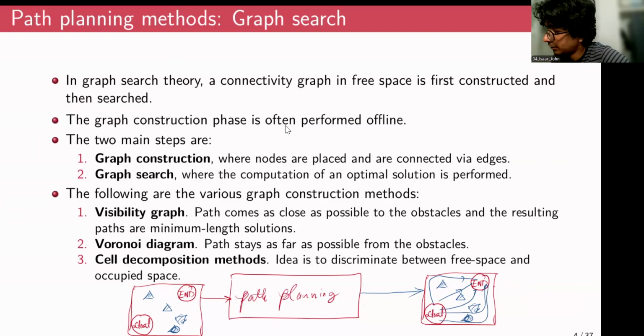This is what we expect from the path planning algorithm, right? Multiple paths. And you may call these road maps, a network of multiple trajectories within that map. And while it has to create this sort of roadmaps, all possible roadmaps, it should also select the most efficient or most appropriate, as well as the most reliable path, so that it can reliably and efficiently reach the end position from the start position. So this would be the input to the path planning algorithm, and this would be the output of the path planning algorithm.